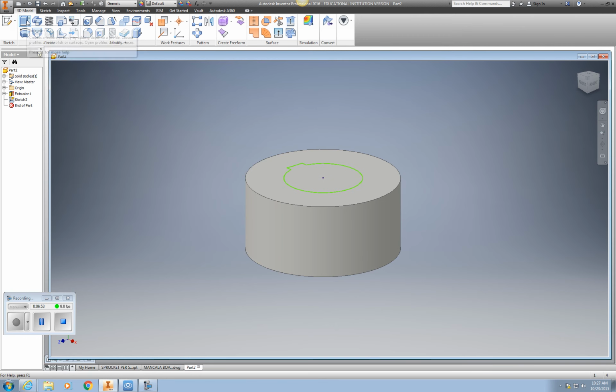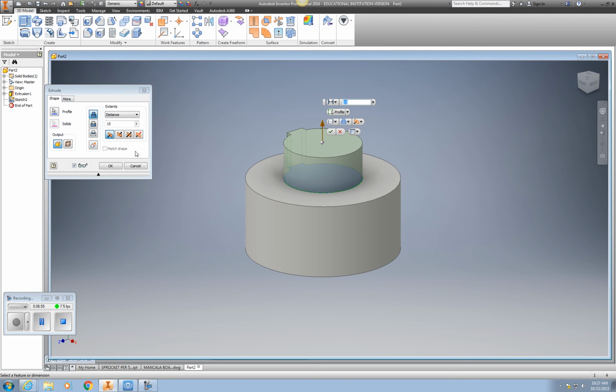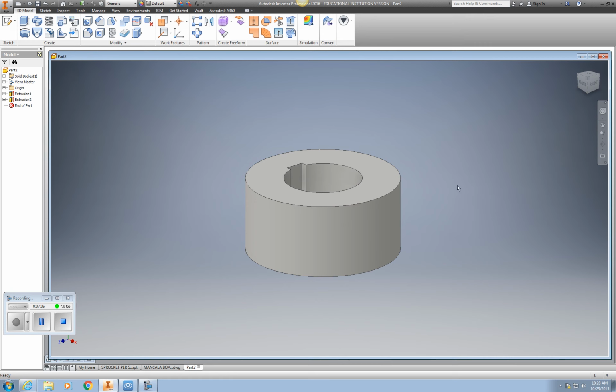So we can go to extrude, select the keyway, direction 2, and our distance will now be all, as you can see here. We can now finish that. Now our next step after this would be to put in the circular outer shape that you can see, and that is going to be a depth of 12 with a diameter of 189.